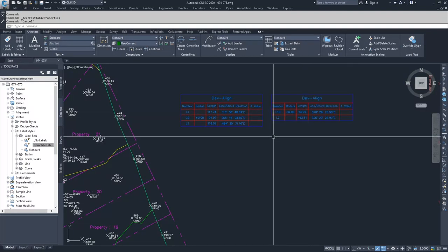And so this is a great thing to have if you have a specific window that you need to have all of your tables fit inside, and you can only fit 10 in a stack before you need to move on to the next stack over. And so say you had 30 segments that you had labeled inside of a table, then you'd have 3 stacks next to each other, and you could do them vertical or horizontal based on the settings that you have for that table information that we went into and modified.